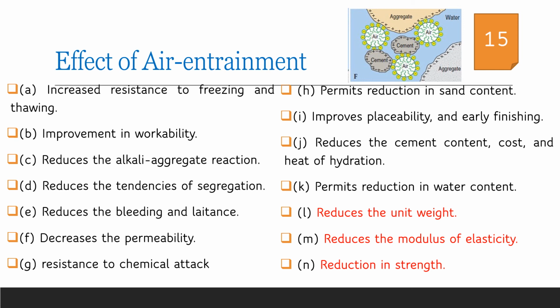But there are some negative influences also. Due to the entrainment of small air bubbles, there will be a reduction in unit weight, which in turn causes a reduction in modulus of elasticity as well as a reduction in strength.